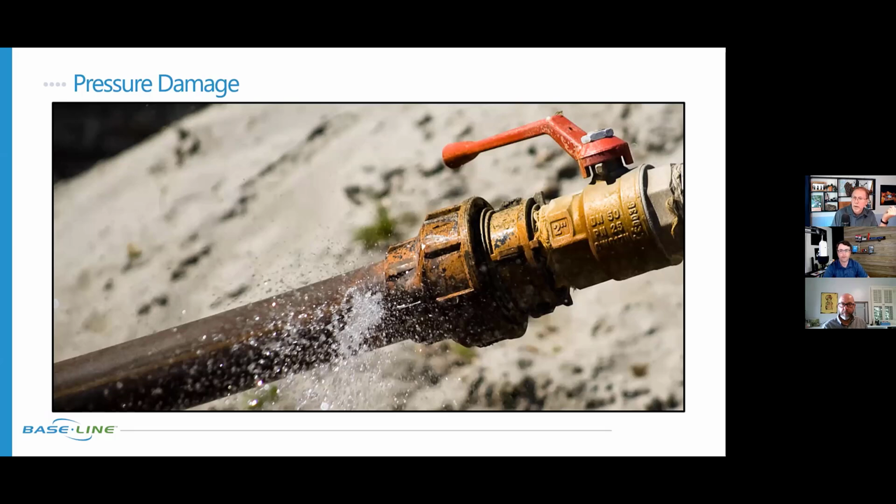So here are 2 ways that we could address pressure issues using a pressure component. When the pressure is higher than 125 PSI, we could close the master valve and isolate everything downstream so we prevent any damage. That's one way to tackle it. Another way to tackle it is when the pressure is higher than 125 PSI, that same level, we could start program 1, and maybe program 1 has 4 rotor zones, and it's going to actually relieve pressure. So 2 ways to solve that problem. One is just closing the master valve, and the other is starting another program.